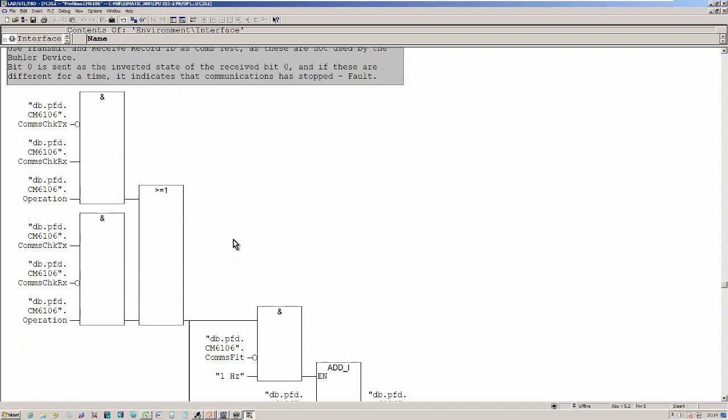And just as an indication, here is FBD, function block diagram. You can see the NOT, there's the little circle. So it's not that and that and that. There's the OR. That is the OR symbol in Siemens, the German way. There's always another way to do it, the German way. And there's this input and not that one and this one. So it works exactly the same.